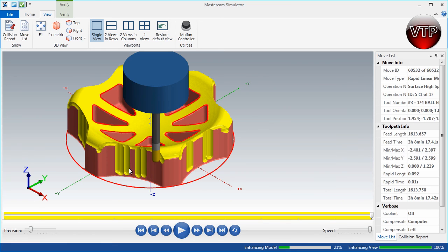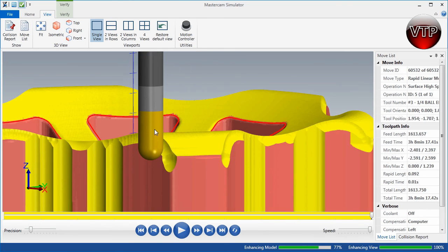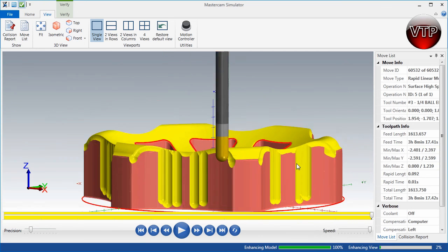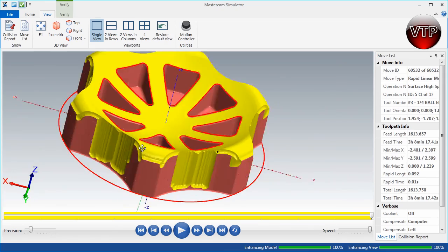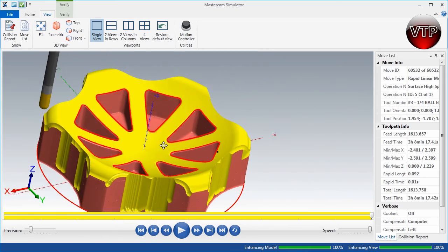The tool will start diving in on the outside of the edge, because remember, we left some stock to be finished on the outside over here that we need to come back and finish later. So we don't want the tool to come in and dig down, especially because the tool is not meant for that. This is a short tooling machining surface on the tool that I'm not going to be able to be digging down like this deep onto my part. That's actually going to be jamming on the top side of my part, and that's very bad for the machine itself and the tool as well.